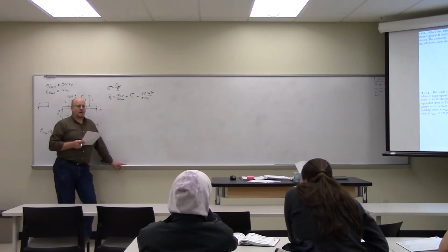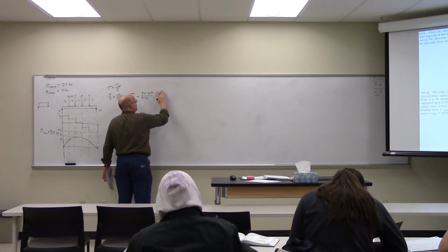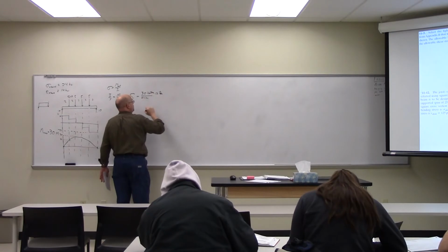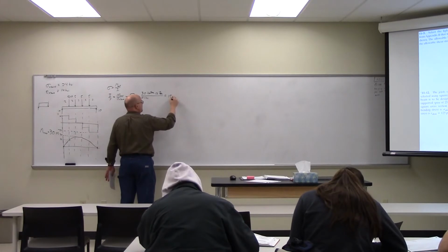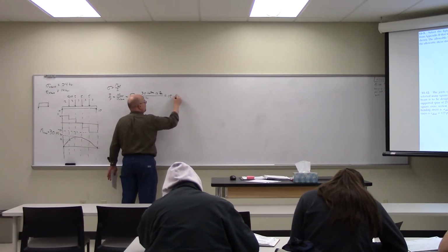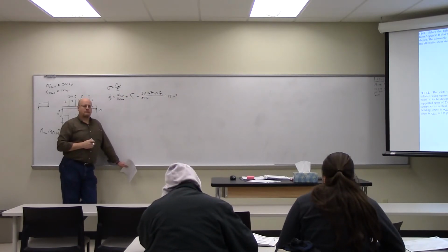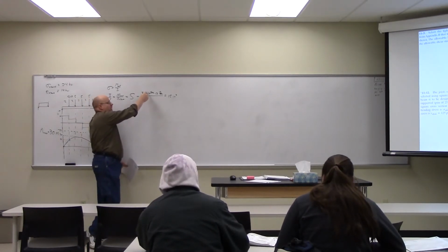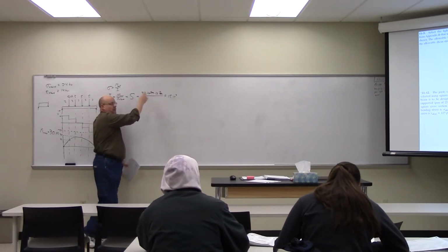Do I need to convert it? Yeah, we have to convert something. Multiply the 30 by 12 to get it in the cubic. Right, so I gotta multiply that times 12 inches per foot. So I get kip inches, so that my inches cancel out. That's 360 divided by 24 is 15 inches cubed. So now what? The kips cancel out. Oh, I see. This is kilopounds, and this is kilopounds per square inch. So kilopounds, and then we get inches cubed.